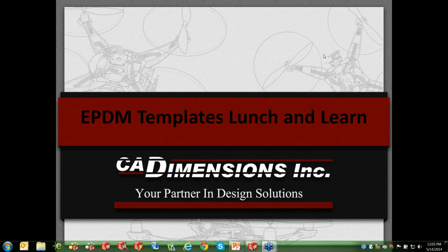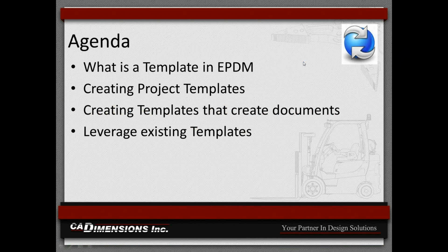Our agenda today is a few things. We're going to talk about what it is to be a template in Enterprise PDM. The term template, we know what that means inside of SOLIDWORKS, but it actually has a different meaning inside of Enterprise PDM, so we'll go through that. Then there are two pretty well documented cases for using templates in Enterprise PDM, and I want to go through the setup process for those. One is how to create projects and project templates. The other is using Enterprise PDM templates to create documents.